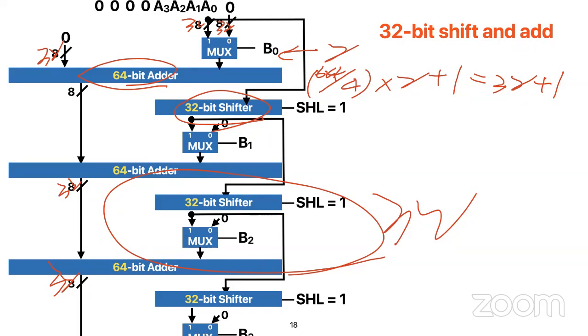Shifters are basically just muxes that reassign the various bits. And if we want to make it a generic shifter, we just need another mux. So in this way, what's the total gate delay for this kind of generic shifter? It's going to be two muxes: one two-input mux and one mux with the input count being however many places you want to be able to shift. So how many gate delays in total? Four.